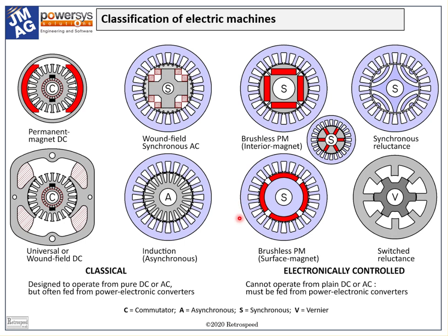But in larger ratings, we sometimes see 6, 9, or even more phases. In so-called fractional horsepower induction motors, we see many configurations with only 2-phase windings, both supplied from a single-phase source, but with means to introduce a phase shift between the currents.